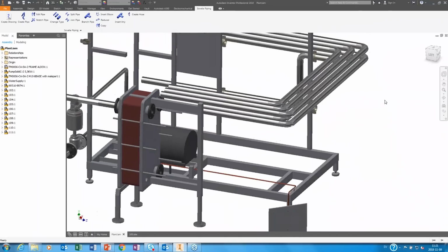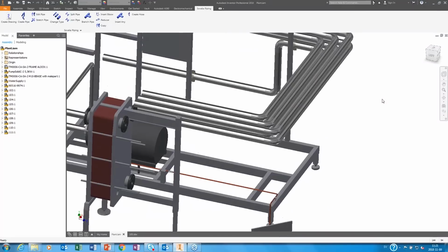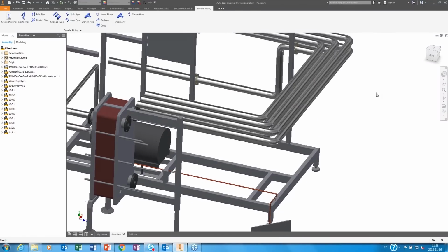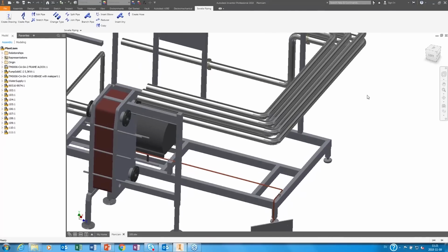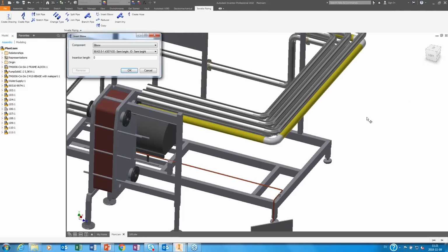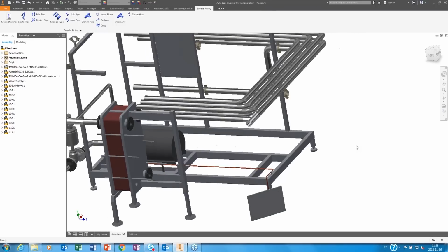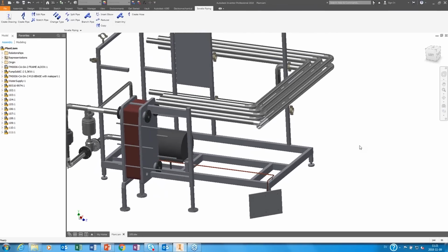And the last thing I will do in this live demo, we saw that we could insert an elbow. We could change an elbow to another one, but it's not the only thing we can do with the insert elbow. If I want to change this one, it should maybe go longer. So I would change from elbow. We could also change to a T. So either it's in this direction or reverse it. I can go in this direction. And if I say OK, you just change it.